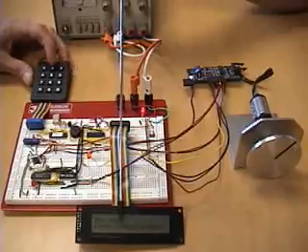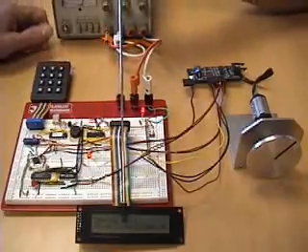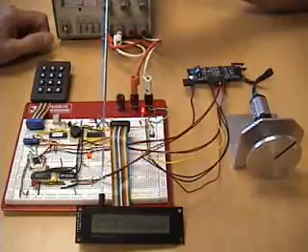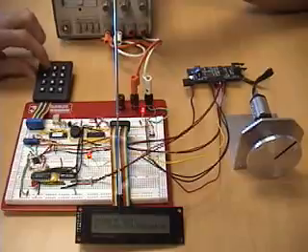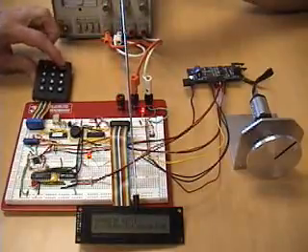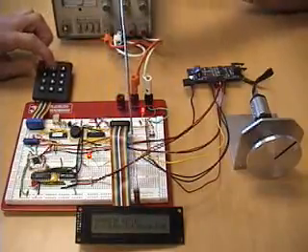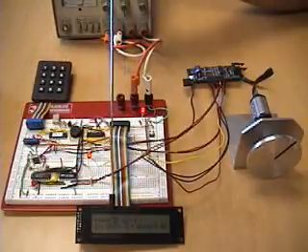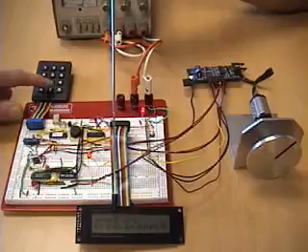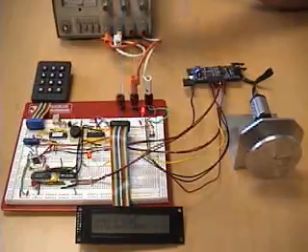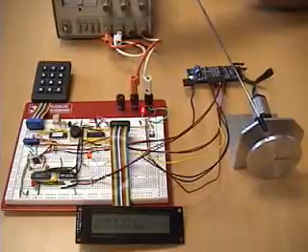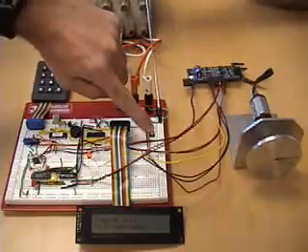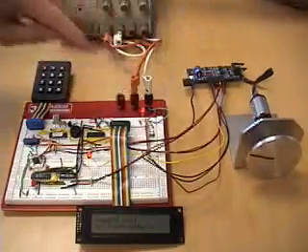Now let's enter the speed control mode. By depressing the second key, we have the option of changing the speed, that's the rate at which pulses are applied to the motor, and whether the motor rotates in a clockwise or counterclockwise direction. By selecting 1, we will rotate clockwise, and by selecting a speed of about 50, we'll get a nominal speed. We execute by pressing 0, and notice the motor then rotates at a constant velocity based upon our input values, and then we can terminate that rotation with the stop button.